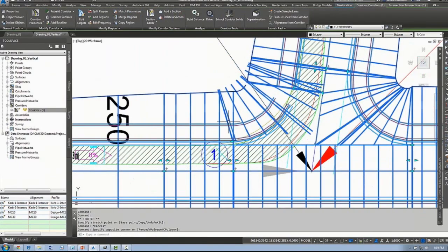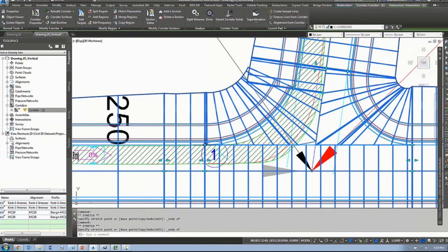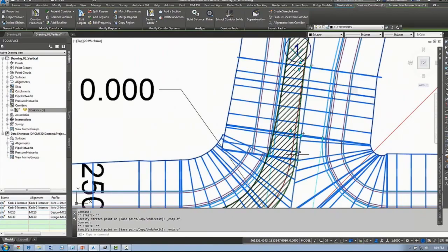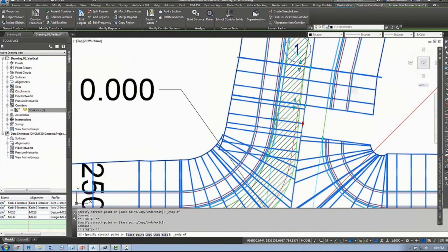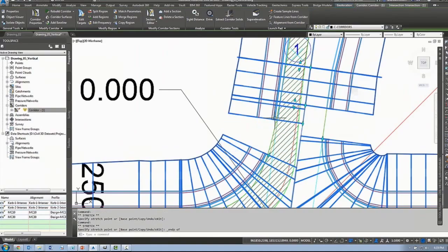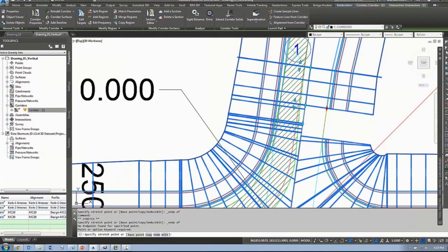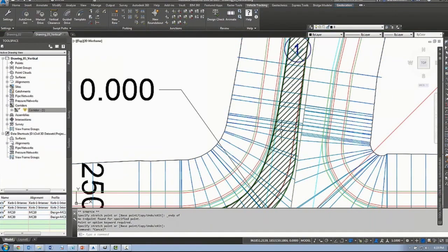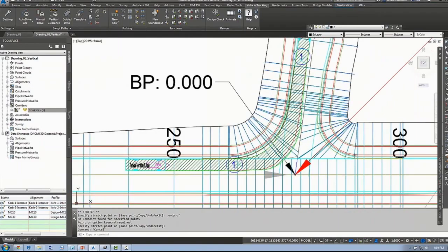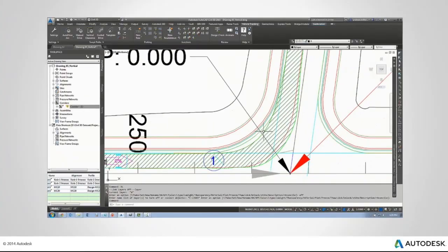So in this case, I'm just quickly adjusting that curve return within Civil 3D. I'm just going to adjust the tie-in locations and rebuild that 3D model. You see that's a very quick process to undertake, just grabbing a few grips, tying them up, and that's it. We've rebuilt the 3D model. Now we can go back in, re-perform the analysis, and confirm that everything works.